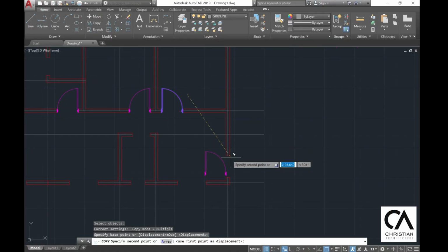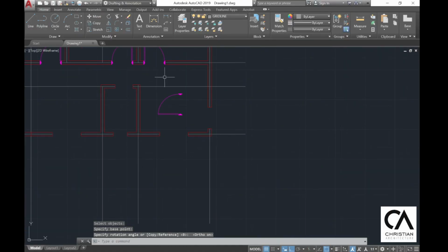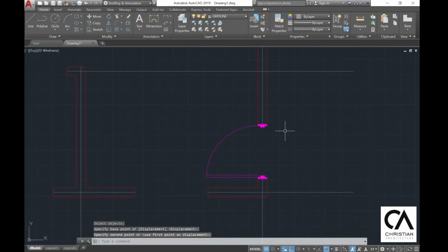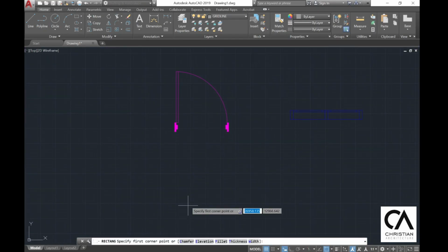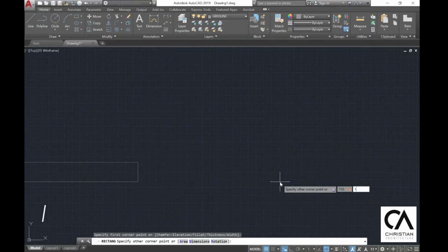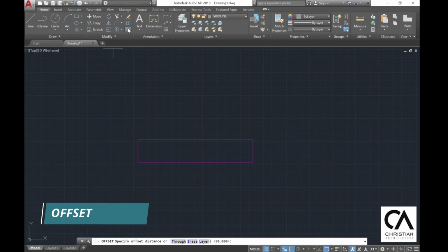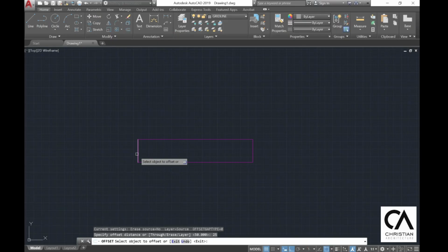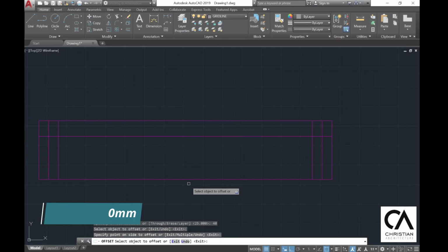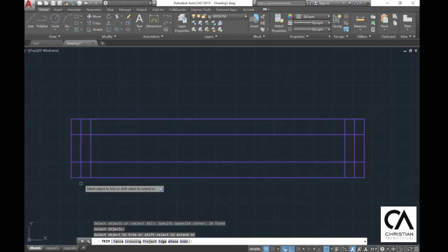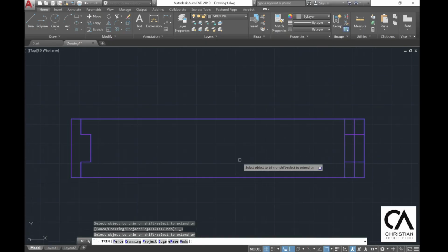Now copy the door, move it into the kitchen area, turn on the auto mode and then turn it off when placing it into the door opening. For the toilet door, the dimension will be 750 by 150. Again, select the door and put it into a door layer. Then use offset 25, enter, and then offset 40. Then select the lines, click trim and remove the unwanted lines.